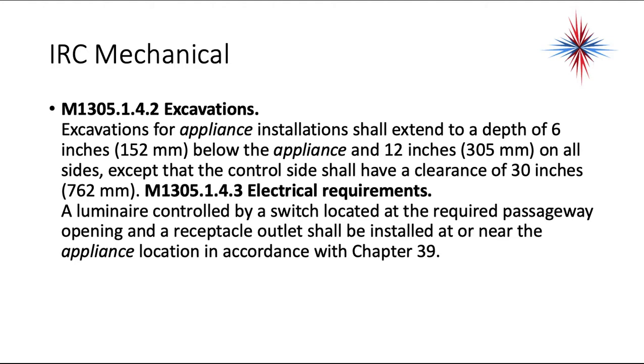Excavation for appliance installations shall extend to a depth of 6 inches below the appliance, have 12 inches on all sides, except the control side, which should have a clearance of 30 inches.